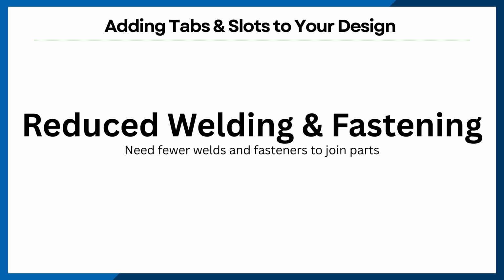Reduced welding and fastening. With tabs and slots, you need fewer welds and fasteners to join parts. For instance, instead of welding the entire length of a corner, tabs can hold pieces in place, allowing for either minimal welds or no welds at all. This reduction lowers costs and minimizes the potential of heat distortion caused by welding.